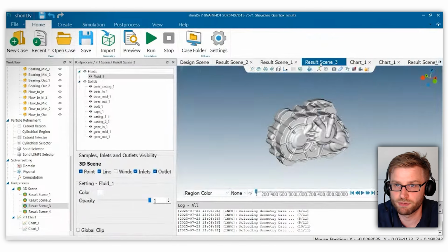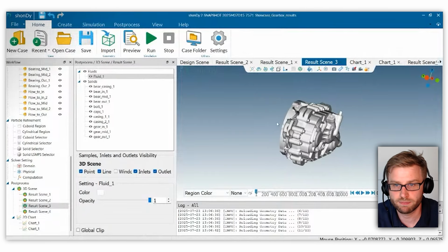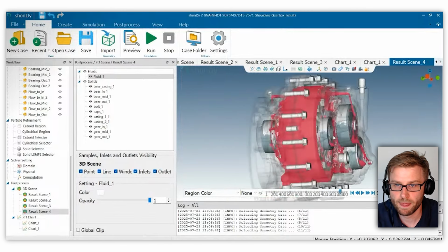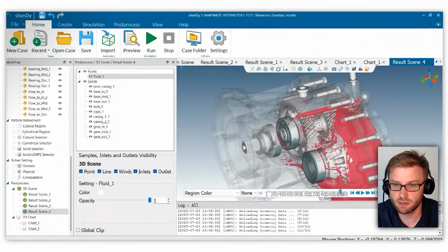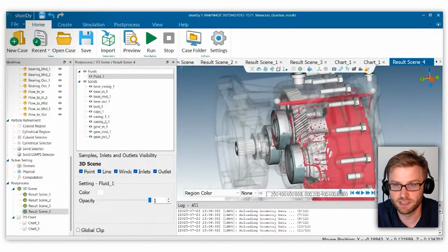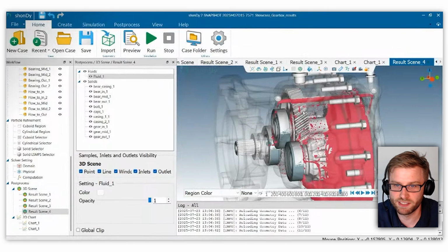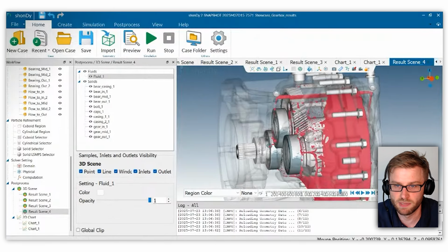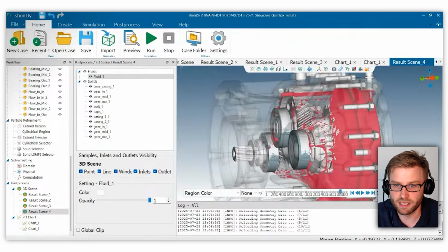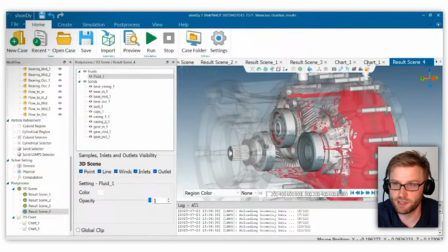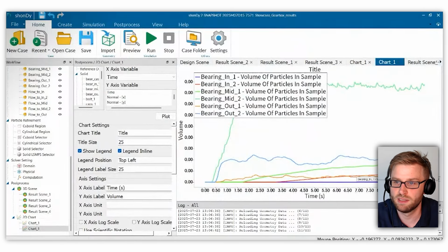This one, in the whole 10 seconds of simulation time, we don't get any lubricant. And if we look at our results, this is this bearing. Sorry, I used to say it wrong. And we can see that from there to there, there's no channel, nothing. So we can see that this is not supported, and therefore we don't get any liquid to this bearing.